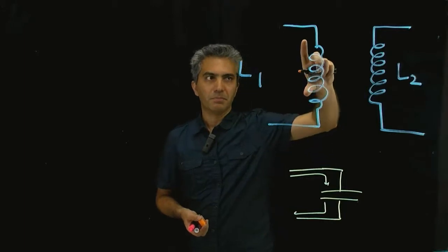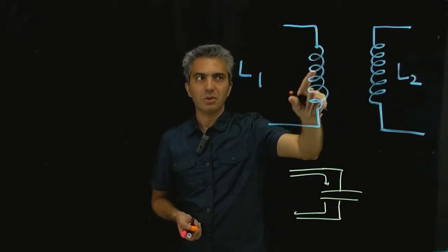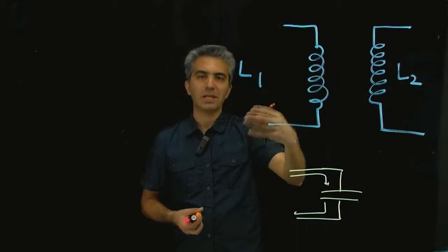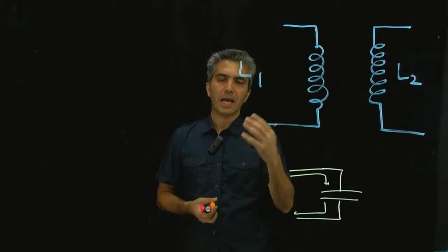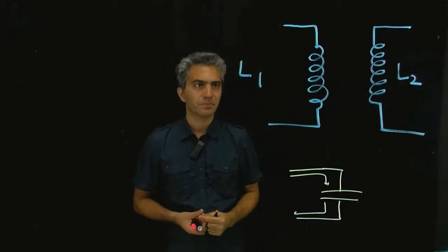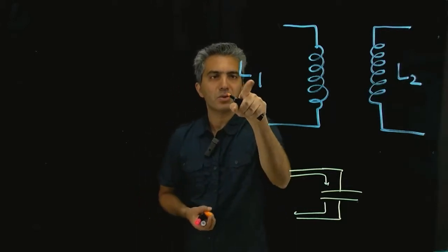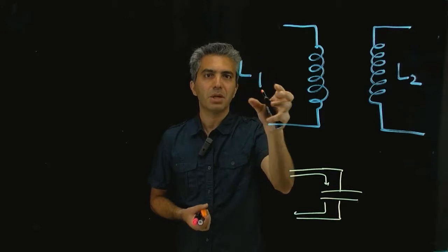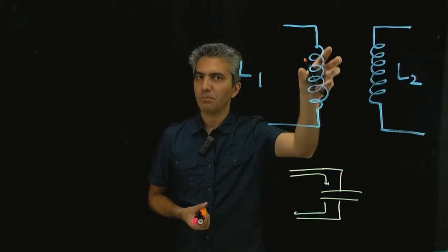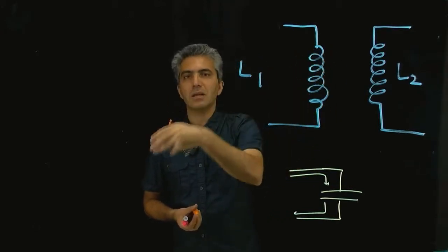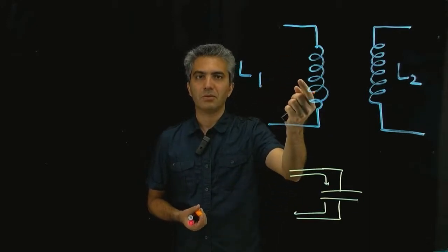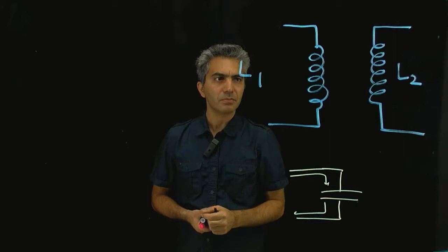But once you turn it into this shape, we reach a point that we no longer can ignore that component of energy. Therefore, there should be a correspondence with this inductance, which is basically a measure of how efficient this component is in turning the energy from the electric domain to the magnetic domain.